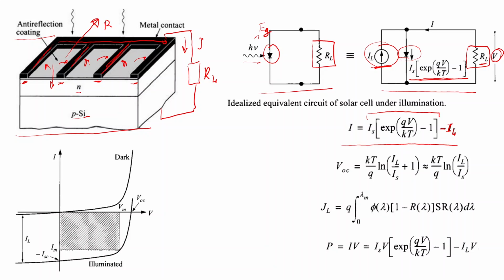You see that if we open this parenthesis, we will have this positive term. It will be the forward branch of the dark current voltage characteristic. And here we have IS, which is the I naught we used previously, the saturation reverse current. For reverse bias, it will be minus IS, because it will be IS times minus unity. So that is our negative reverse current.